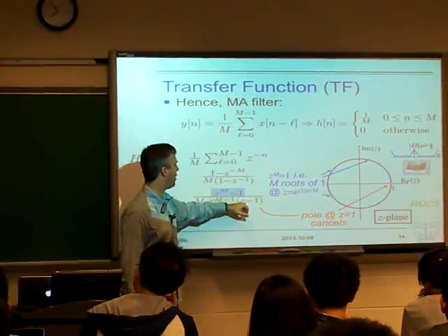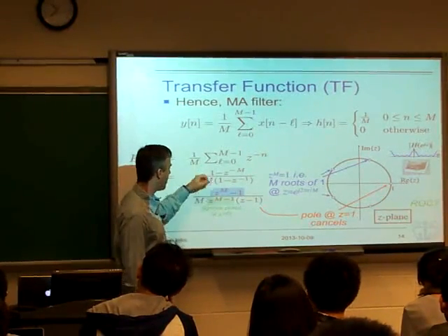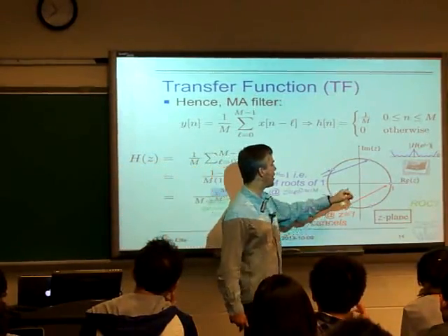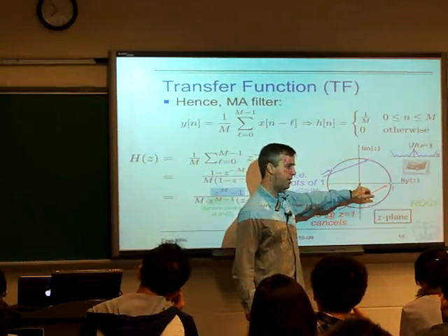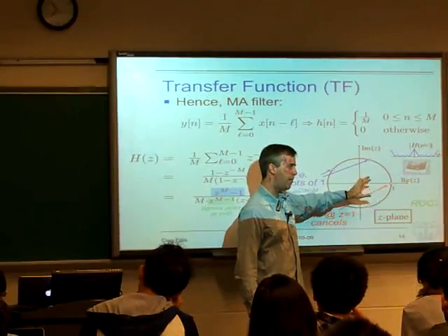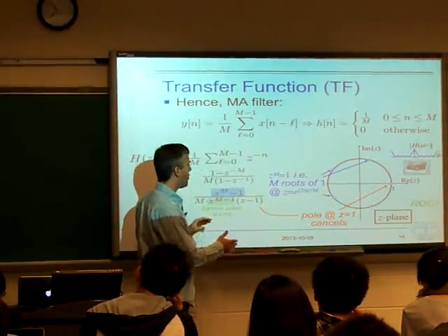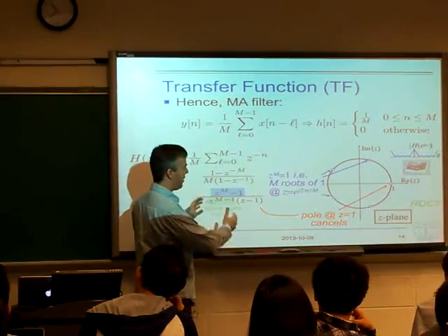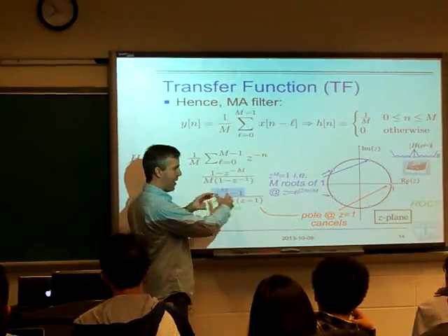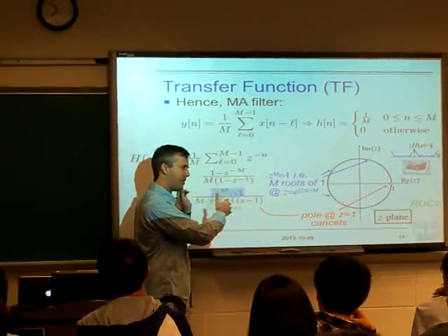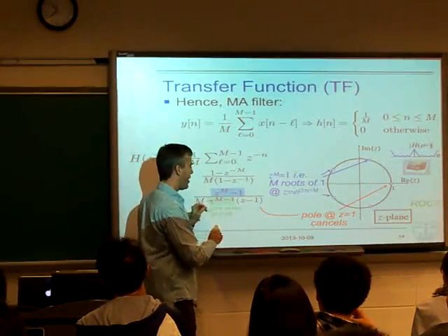Looks like we have a pole here. If we have a few poles, if we multiply this through, we have a z to the m minus 1 term, so we have m minus 1 poles at 0. But like I say, we're going to ignore those. What that means is we could have shifted the sequence by some number of points if it was a sequence, and we could cancel those out just by shifting in time. So they're not that interesting.